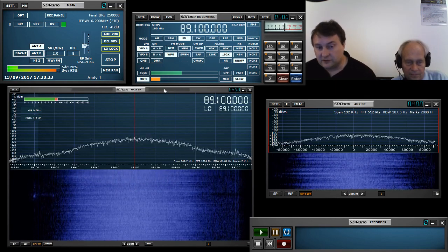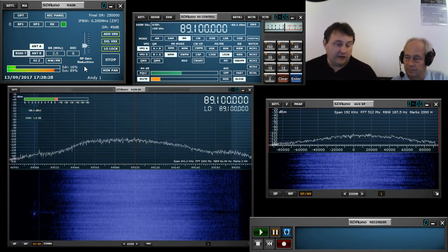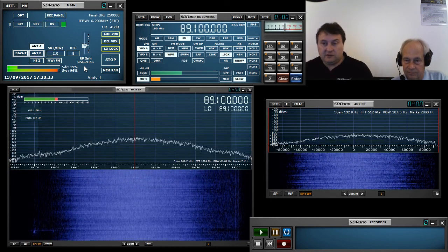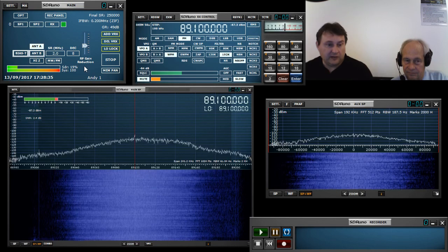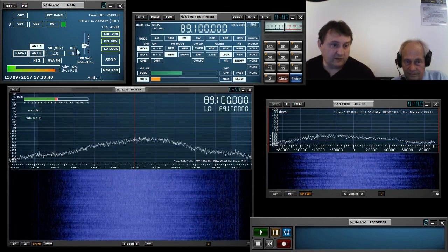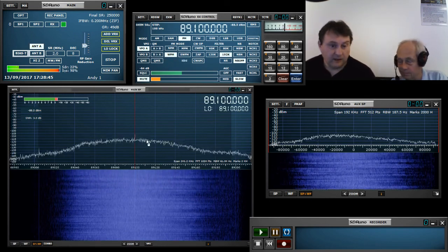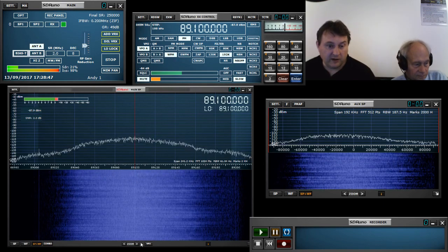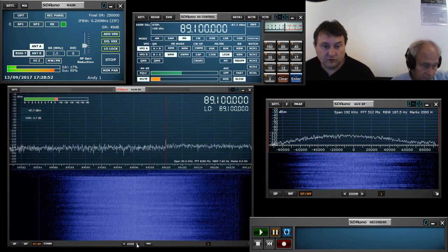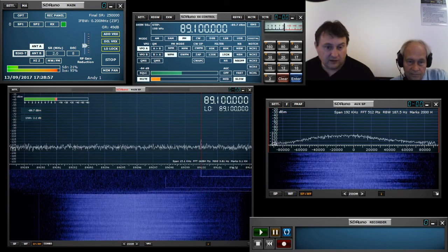It will also help on the CPU load, because the API that is in SDRuno is very efficient. Rather than viewing 10 megahertz of spectrum and then using SDRuno to zoom in on that spectrum, which is very inefficient, it's better to specify a high decimation factor in the main window to lower the final sample rate in the first place. And then once I've got 250 kilohertz of bandwidth, I can still use the SDRuno zoom factor to go in quite a lot, we've got 30 kilohertz now, 15 kilohertz, and so on.